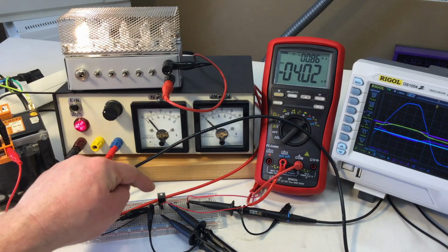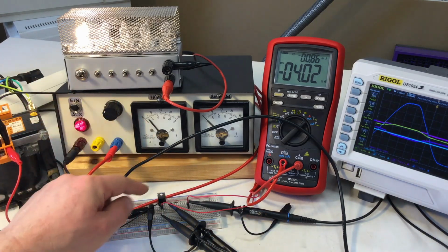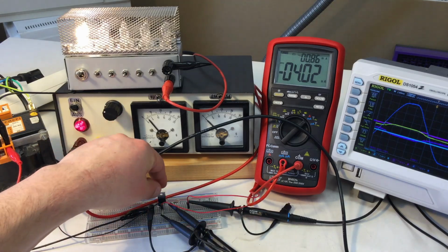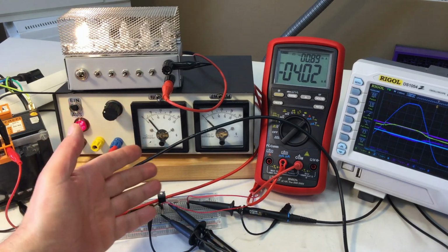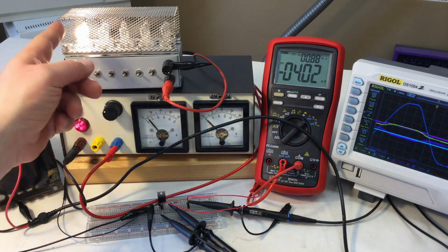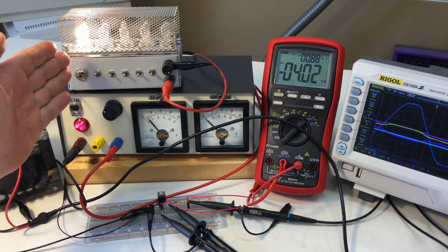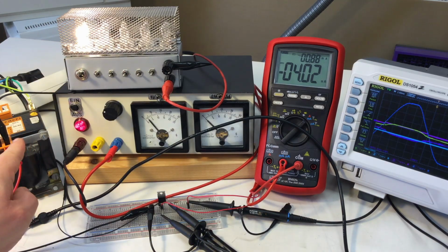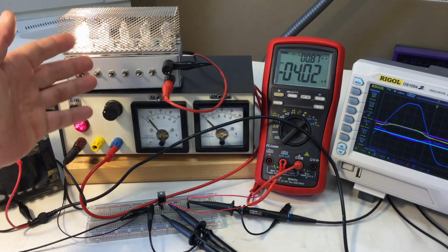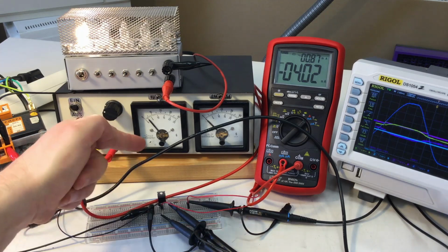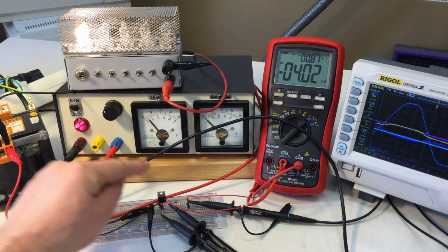But enough about driving the gate with, for example, a microcontroller. I have another problem here. My TRIAC is getting toasty, and I'm just driving 20 watts of light bulbs here. That transformer should be able to drive the full 100 watts I can switch here, but that would certainly kill my TRIAC. So we need some cooling.